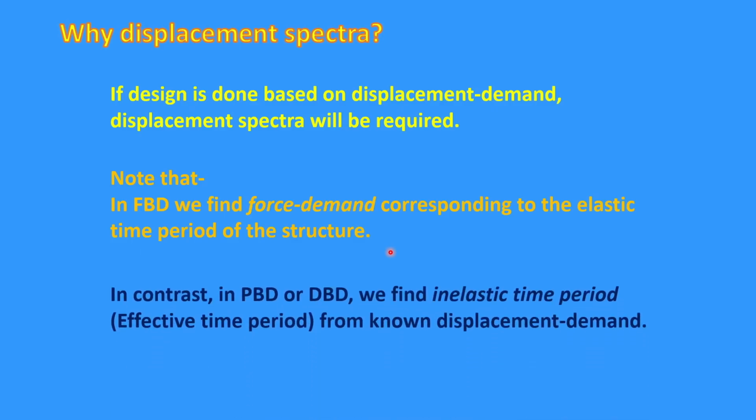In contrast, in performance-based design or displacement-based design, we find the inelastic time period. What is this? We shall see in the next slides. From the known displacement demand, here the displacement demand is known to you, we have estimated it through some engineering process, and from this displacement spectrum, we shall find out the inelastic time period associated with the system and then proceed for the design.